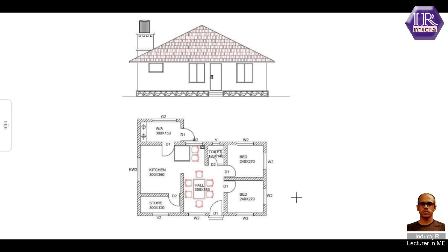Even if I said that we will be using either first angle projection or third angle projection for a 3D object, in the textbook you can see there are questions relating to the second quadrant or fourth quadrant for projection of points and projection of lines, and those are given so that you can have a better understanding of this multi-view projection in different quadrants, and also you should be very familiar with the concept of rotation of the HP. In reality, for a 3D object, you will only be referring to either the first quadrant or the third quadrant.